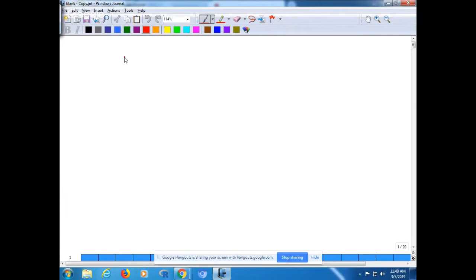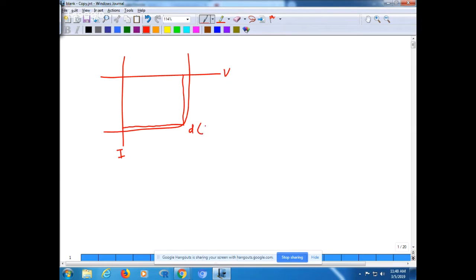So fill factor is, if this is the IV curve, this is V, this is I, the rectangle that you can draw inside it corresponding to d(JV)/dV equal to 0. So this point is the maximum power point at which this derivative is equal to 0. The maximum possible voltage and current available is ISC into VOC, but what you get according to this is VM into IM.